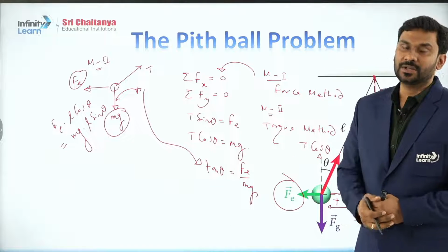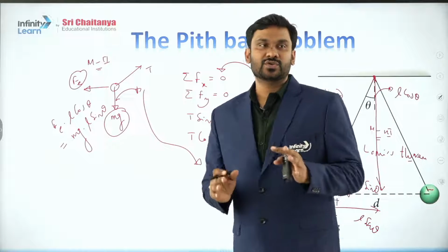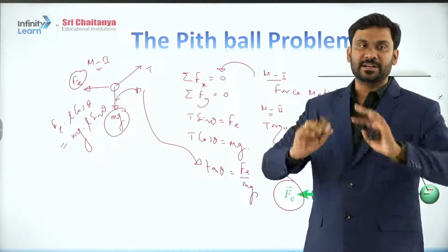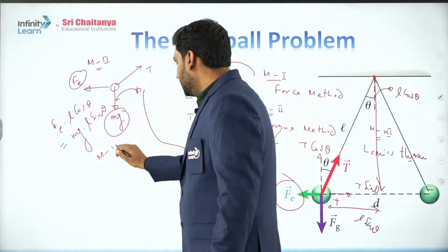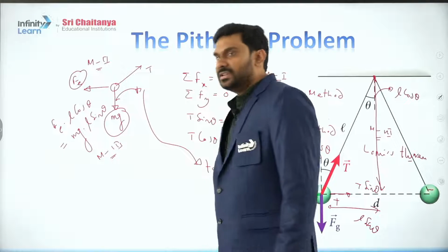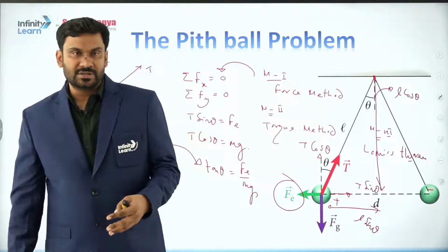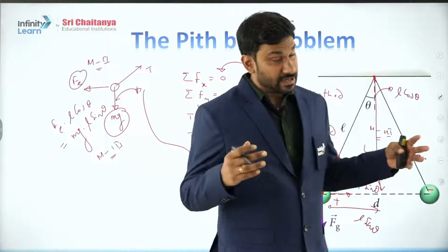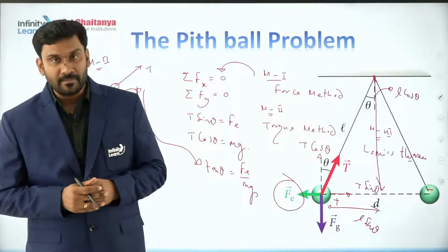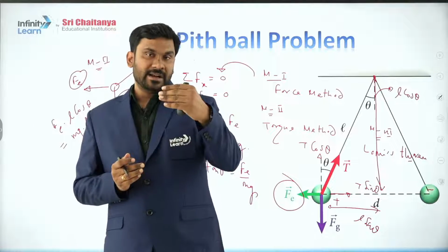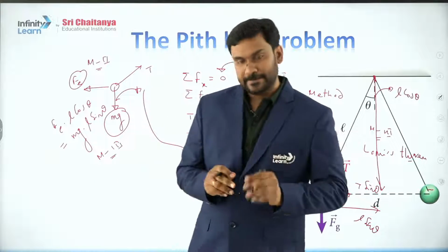There is no deviation of the ultimate final answer. So that means both the processes are correct. Yes, they are correct. I have just shown you two strategies, two different ways how to see that perspective, right? Fine. So now if I look at method 3, I have told this is Lami's theorem. What is Lami's theorem? Lami's theorem says that if three forces are setting up equilibrium, or if they are passing through a common point, if they are concurrent, then they will establish equilibrium of a system. So in that case, force vector divided by sine of opposite angle becomes constant. That's Lami's theorem, right?